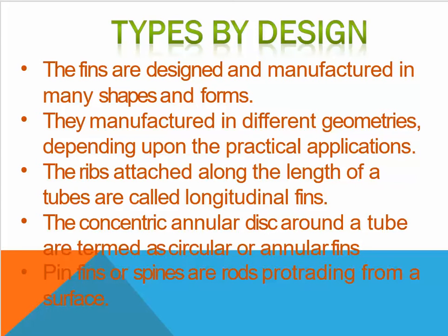The ribs attached along the length of the tubes are called longitudinal fins. The concentric annular discs around the tube are termed circular or annular fins. Pin fins and spines are rods protruding from the surface.